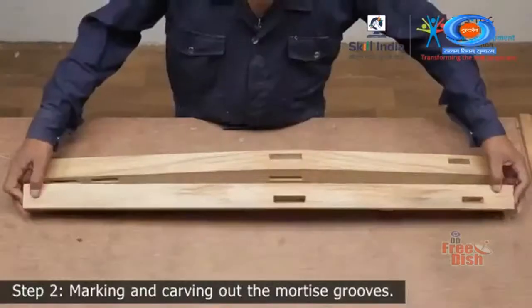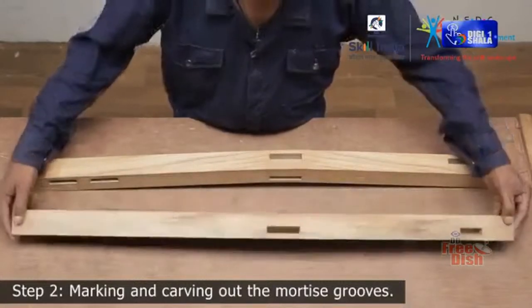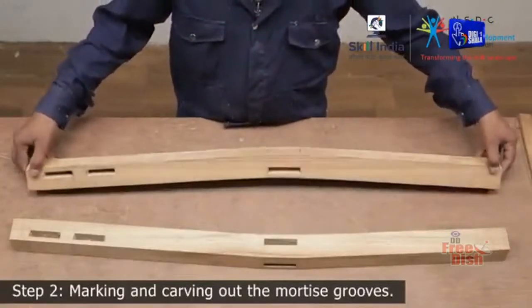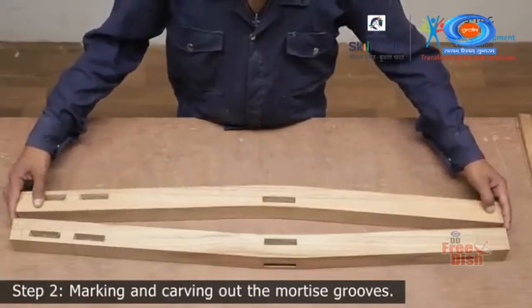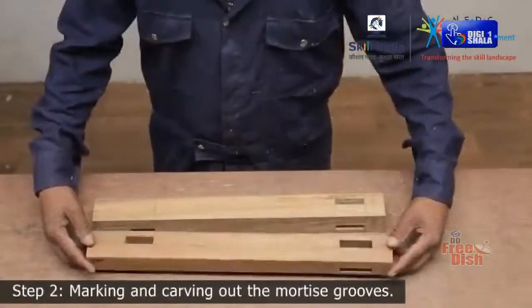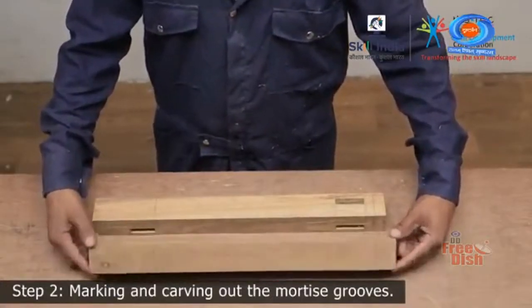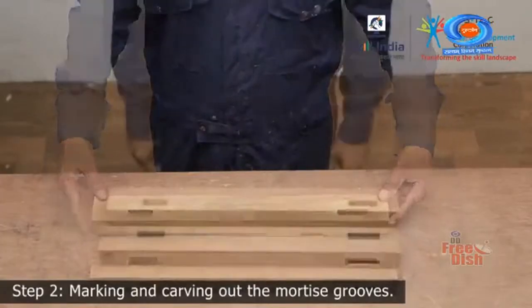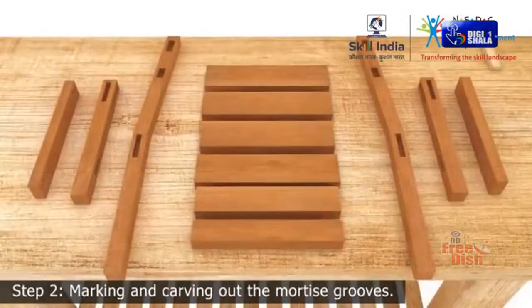Use the same process for carving out all the mortises on the other side as well. And you are ready with the back leg with the mortise grooves. Similarly, repeat the same process for carving out all the mortises on the other back leg piece as well as the 2 front legs. When you are ready with the mortise grooves, you need to work on the tenons.